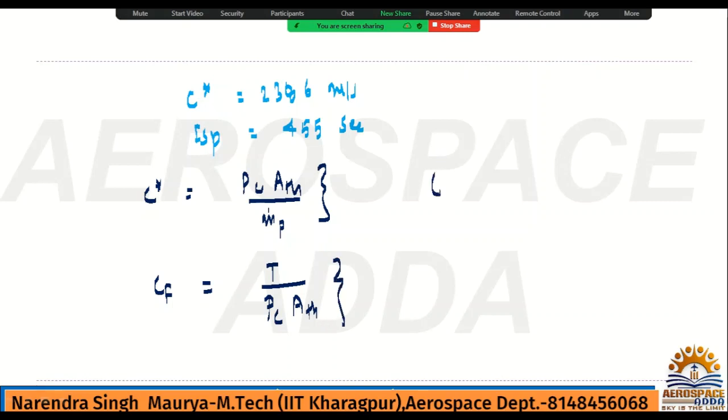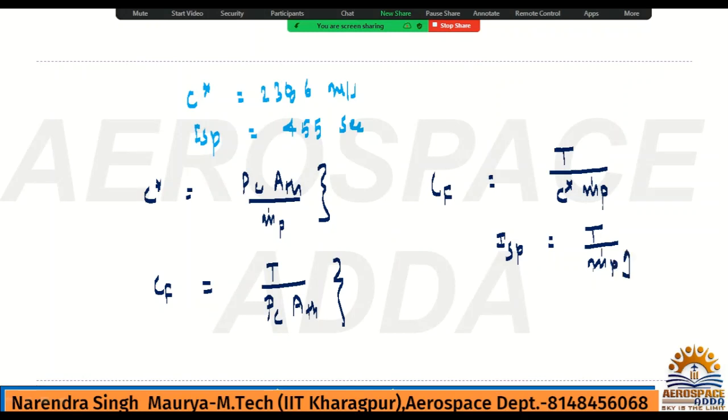CF is nothing but thrust divided by PC A_th. PC A_th will be C star into M dot P. And the formula of ISP is thrust divided by M dot P into g.